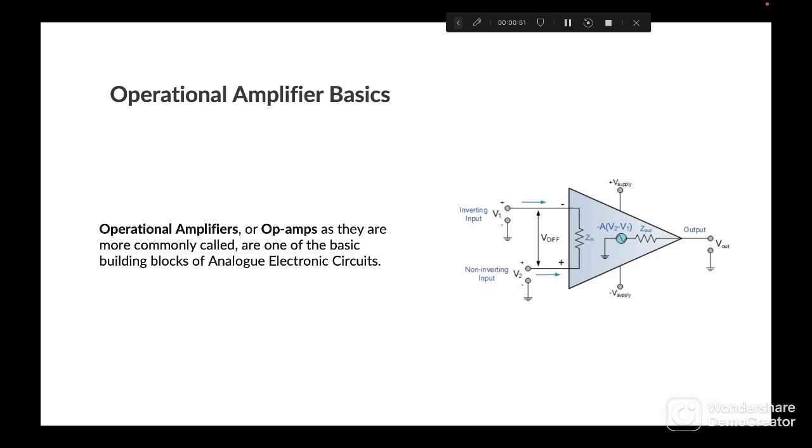An operational amplifier, or op-amp for short, is fundamentally a voltage amplifying device designed to be used with external feedback components such as resistors and capacitors between its output and input terminals. These feedback components determine the resulting function or operation of the amplifier, and by virtue of the different feedback configurations, whether resistive, capacitive, or both, the amplifier can perform a variety of different operations, giving rise to its name of operational amplifier. An operational amplifier is basically a three-terminal device which consists of two high-impedance inputs.